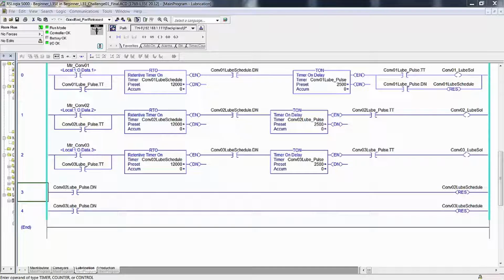In the manual, it shows 2 columns, inputs and outputs. Input 0 through 5: system start push button, photo eye conveyor 1 entrance, photo eye conveyor 2 entrance, photo eye conveyor 3 entrance, photo eye conveyor 3 exit. And then input 5 we may or may not be using, depending on whether or not you used it for downstream request. I think I had you do that in the manual, but it wasn't necessary. You could always toggle it, right from your keyboard, because we are really simulating this.